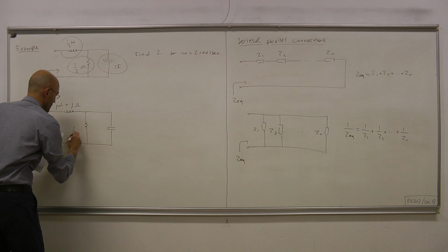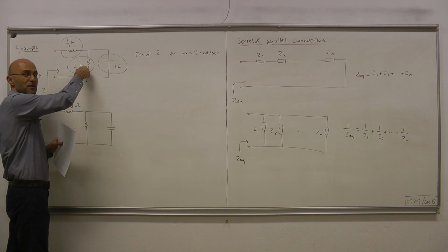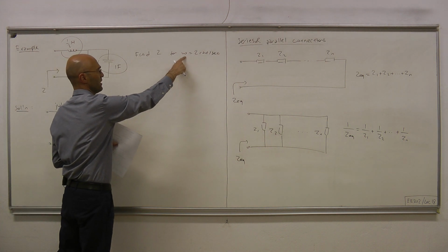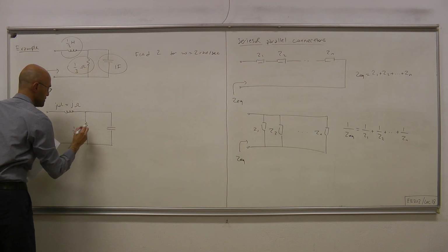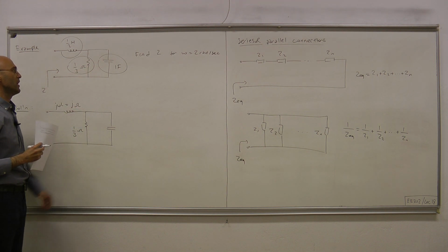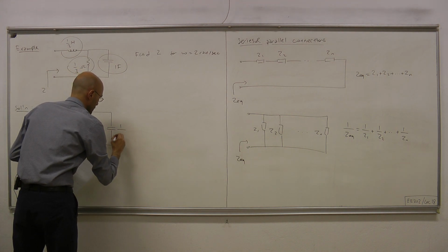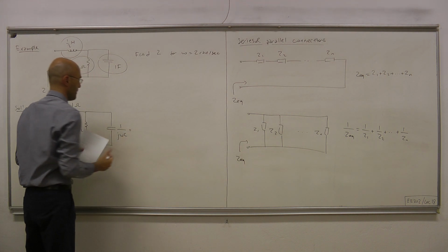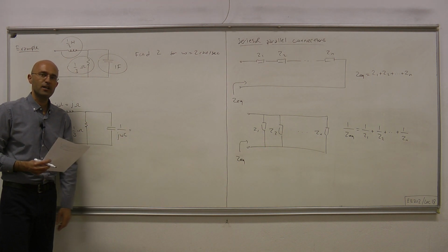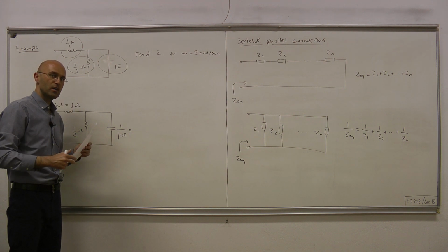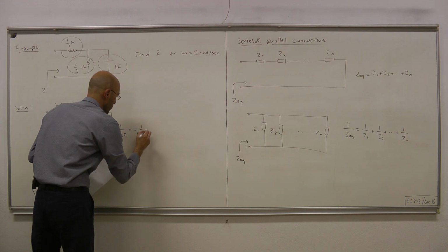Likewise, the impedance of the resistor directly equals the resistance. It's independent of the frequency, so we just copy whatever we see here, 1 over 3 ohms. And as for the capacitor, the impedance is 1 over j omega C. C is 1, omega is 2, so what we have is 1 over j2. That j we can carry upstairs and write minus j times 1 over 2.